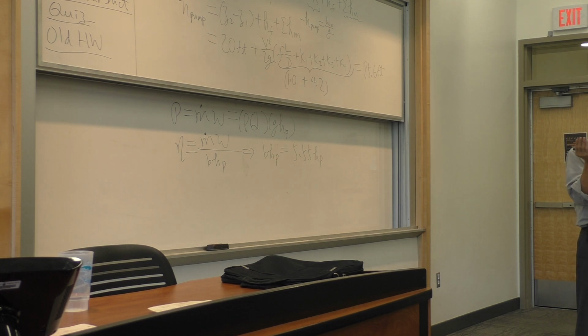And for this kind of estimate, as an engineer, you really don't care whether it's 6 horsepower or 5.5 or 6.5. You go buy a pump, you probably don't find something that's exactly 5.55 horsepower. So for the spirit of an estimate within 5–10% accuracy, you're done. But if you're building an aircraft engine, you won't be done. You can't be good enough within 5% or 10%. You got to be good enough within 1%, because the plane won't fly. You have overestimated all these frictional losses.